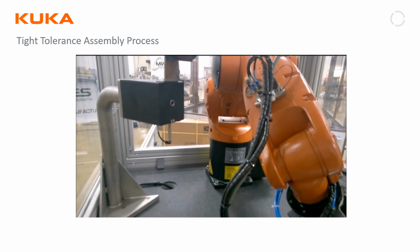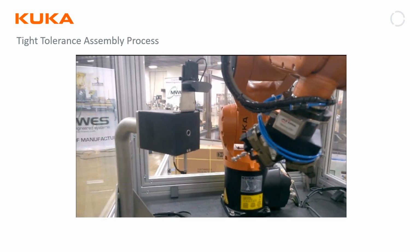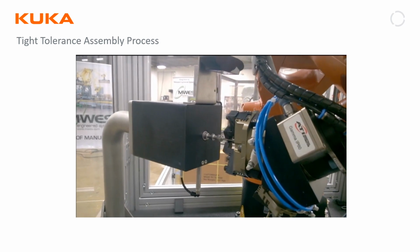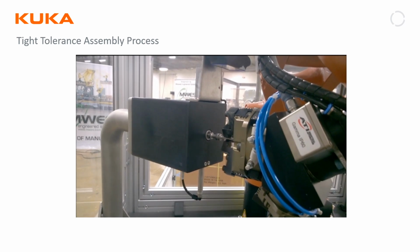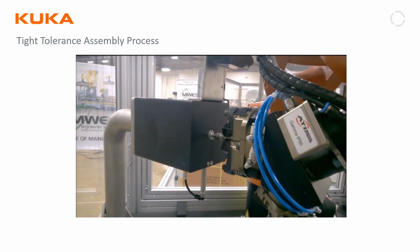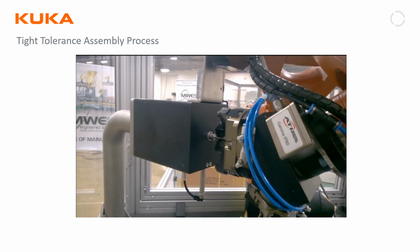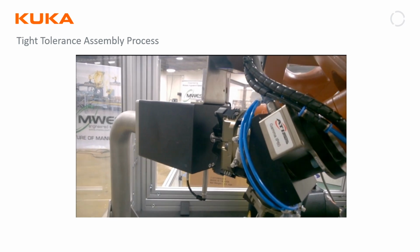Altogether, RSI and force torque add some really powerful capabilities to KUKA industrial robots. This final video shows insertion of a bobbin into a valve body. With RSI and force control, this assembly is reliable, even though the fit tolerance of the parts only has a few microns of clearance. With sensor feedback in the control loop, we can achieve performance way beyond the positioning accuracy of any industrial robot.